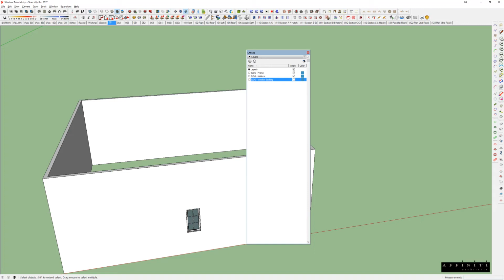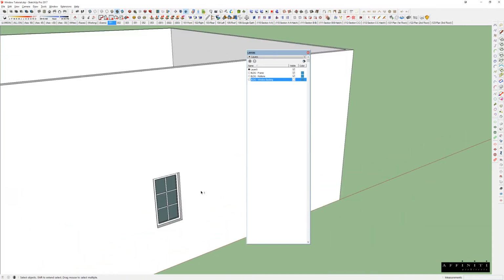So that was the first reason why I built this window backing, was so that I can work with these windows in two different ways of modeling. And if I do two-dimensional elevations, I don't necessarily want to see through the windows and see all the windows behind, because then it's just going to create a lot of odd geometry, and we'll really see more of that in a minute. So this way, when I do my 2D elevation views, I can put window backing on so I don't see through my windows. So hopefully that really starts to make sense.